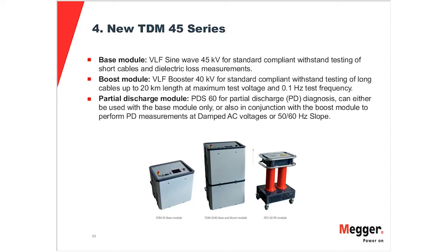Then the middle part is the so-called boost module. It consists of a VLF booster, 40 kV RMS, not peak in this case, for standard compliant withstand testing of long cable, in contrary to short cable with the sinusoidal, up to 20 km of length at maximum test voltage. Then the last module is the partial discharge module, which we are using for PD diagnosis. It can either be used with the base module or it can be used with the booster.